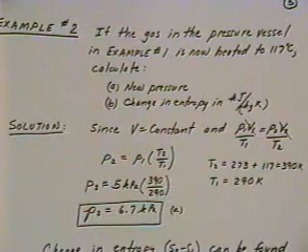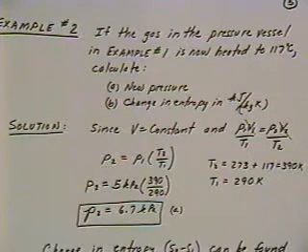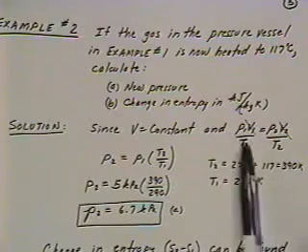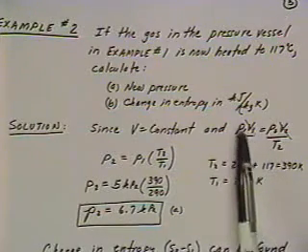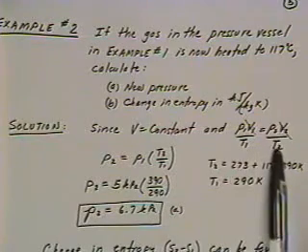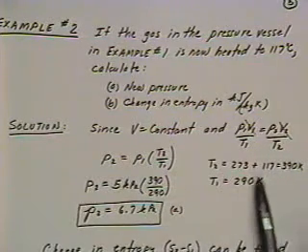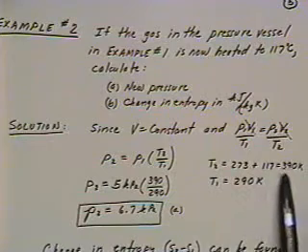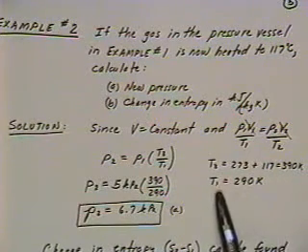Okay, so we can go back to our perfect gas law equations. Remember on the previous page we had the relation on the gas laws that P1 V1 over T1 is P2 V2 over T2. In this particular case, since we're working with a rigid container, the volume stays constant. We're not doing anything to the mass of the container or the volume, and so we can cancel out our volumes, and we have a straightforward relationship then that P1 over T1 is P2 over T2. We know temperature is 273 plus 117, which is 390, for the T2.